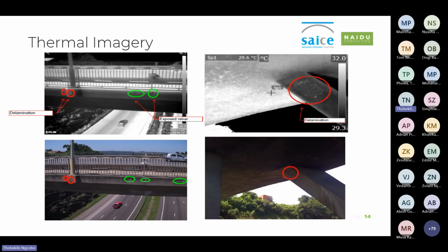So we used thermal cameras to scan the surface and detect those heat differences, as you can see on the screen at one of the piers. This allowed us to map out delamination zones correctly. And that's what's powerful here: the process is non-destructive, it is fast, and it is quantitative as well.